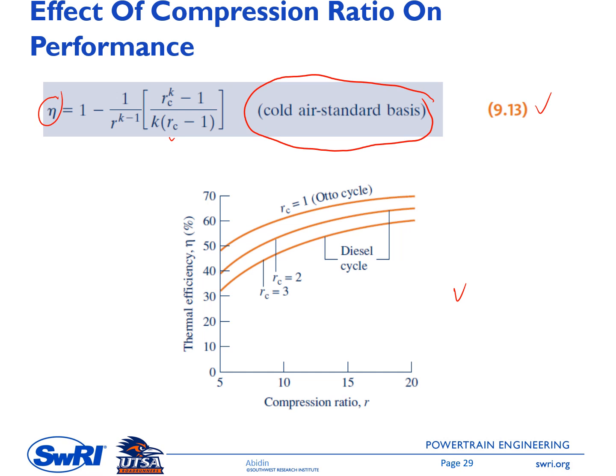Looking back again at the previous slide, this one equals 1. So look again at this chart. You have thermal efficiency as a function of the compression ratio. For RC equal to 1, which means V2 equals V3, you have the Otto cycle here.